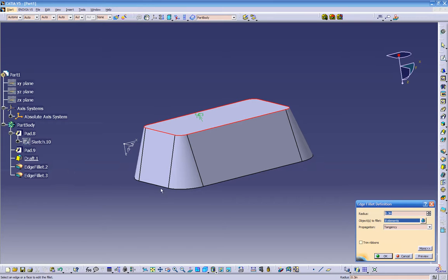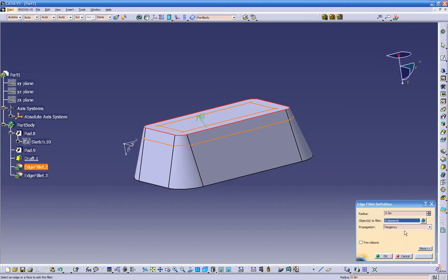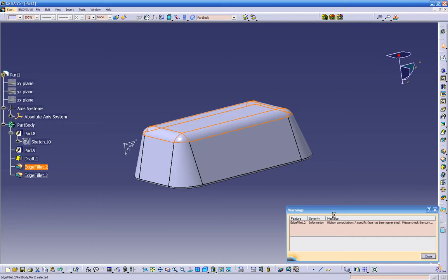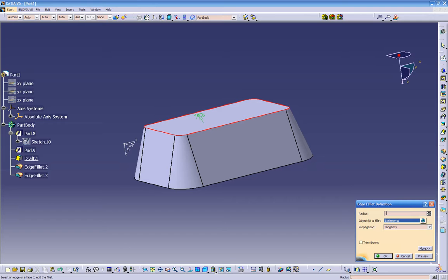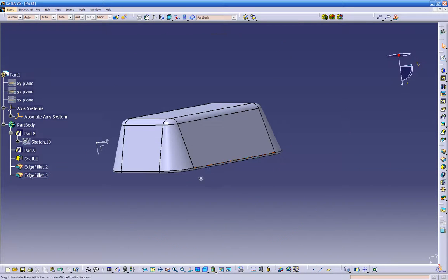Double click on the fillet, same thing, we can change it to 1/2 inch. Let's do a preview. Oh, it's just too big, so it doesn't like that because it overlaps. So let's make it a little smaller. Let's make it 350. So that's our little radius, still too big. So let's make it 300. Actually, let's get a little smaller, 250. Click OK.